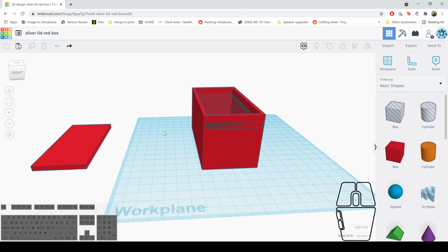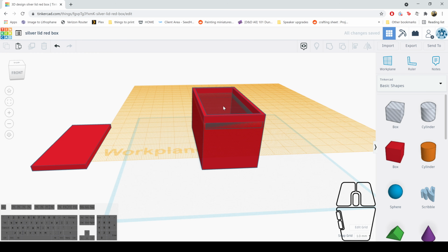All right, so let's knock out this piece up in the front here. The easiest way to go about this is to place a whole object directly on top of our lid insert, and then align and group everything. So first thing we want to do is bring up the work plane. The button for it is right up here where my cursor is. I'm going to use the keyboard shortcut, which is W, and move the mouse around. As you can see, we're now dragging around this little translucent plane. We're going to place that directly on top of our lid insert, and just left click.